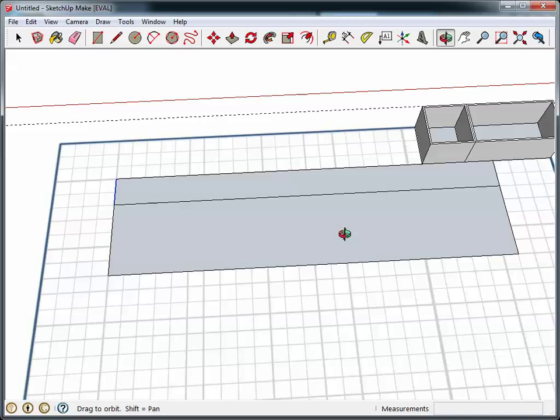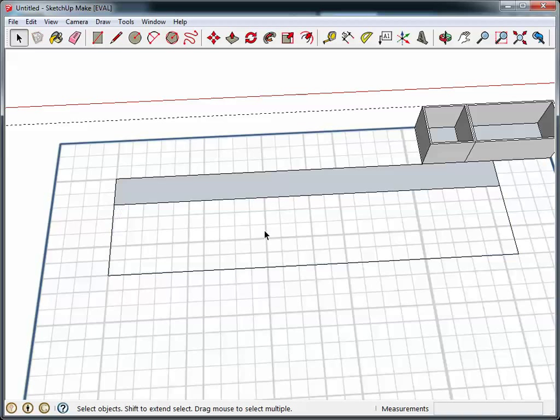All right, and I really can't see the grid down here below, so what I can do is select this and hit the delete key, and it clears it off, but it leaves my lines in place there. And I can use the pencil to draw in the rest of the 10-foot wide hallway. Didn't quite hit that exactly. I could hit escape, and Control Z to undo that. See if I can get a little bit closer on my pin placement.